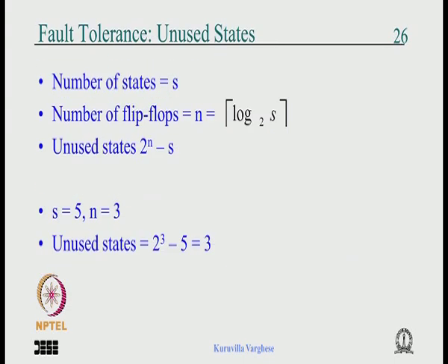Now let us come to the next issue. What we have discussed is state assignment to reduce the area, and we have found that evaluating all possible state assignments to come out with a minimal area is an intractable problem. We have seen the huge computation time required. So we came out with some heuristics which are based on sensible basics of minimization. So it should work.